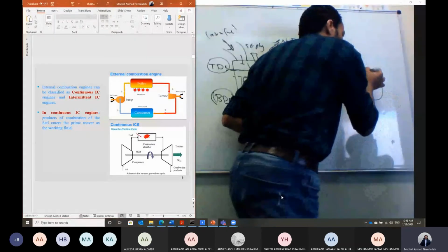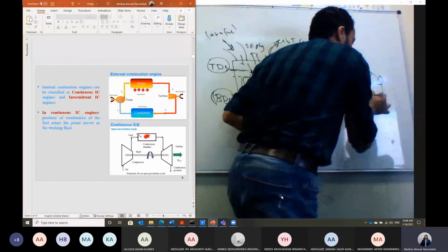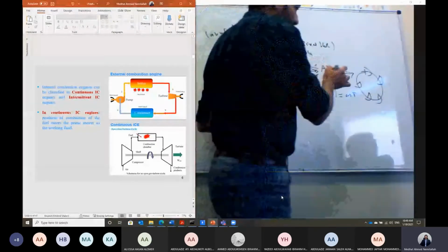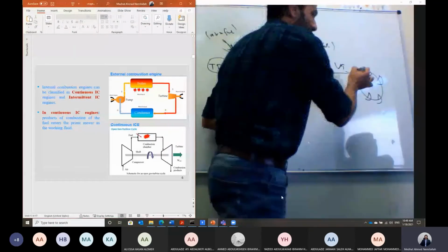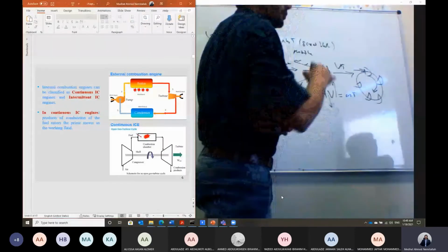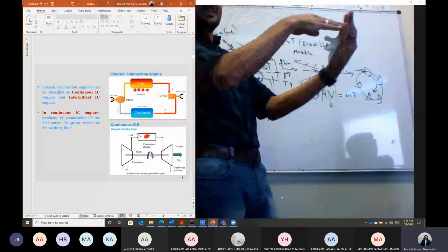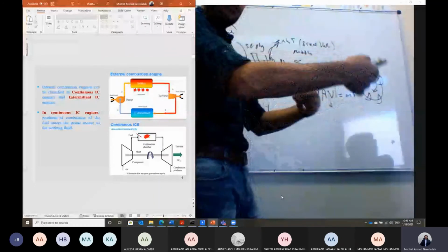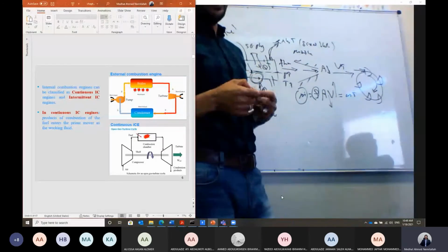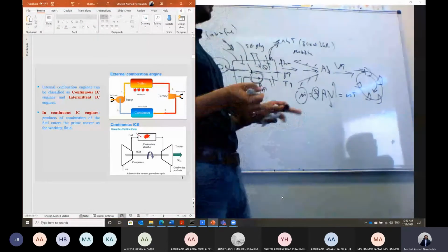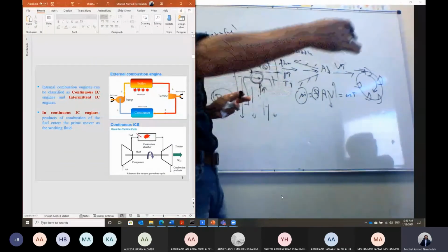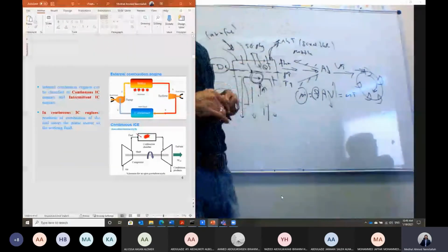Then there is a rotating shaft of the gas turbine, on which we have an impeller, and on this impeller we are fixing blades. So the flow will be leaving with very high velocity. It will hit this bucket, and there is an impeller here on the shaft. It will hit the bucket, forcing the shaft to rotate and generate shaft power. And usually, Shabab, the gas turbine is not only one row of fixed blades and one row of moving blades. It consists of different rows, a number of rows in this case.